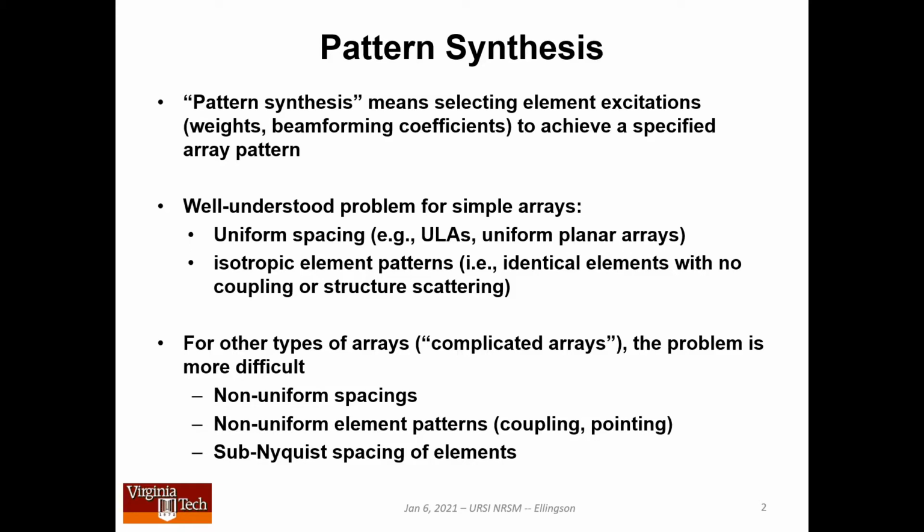Or perhaps you have an aperture which is not fully sampled in the Nyquist sense. For example, element spacing significantly greater than 1/2 wavelength. In these cases, the options for pattern synthesis are not so clear. Let me show you an example of such an array.